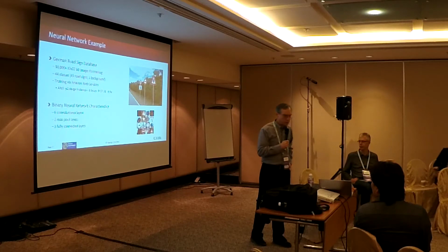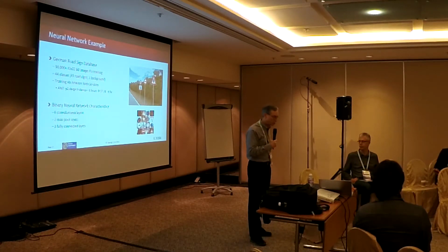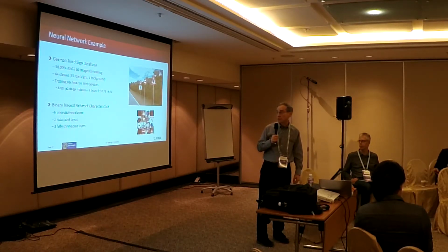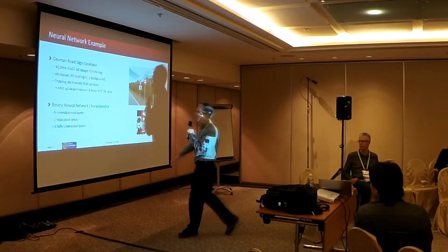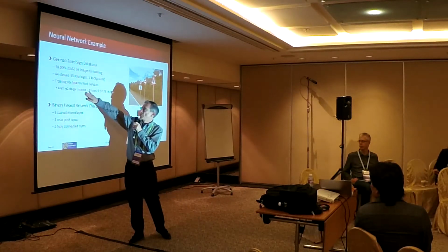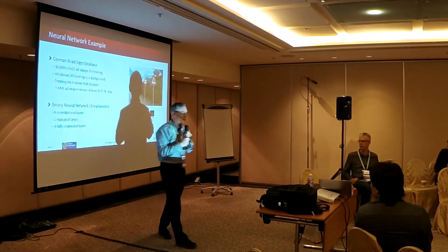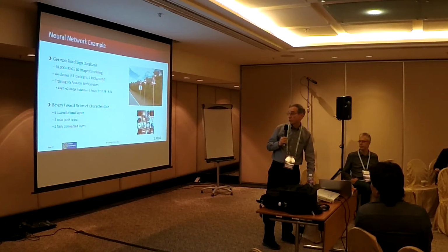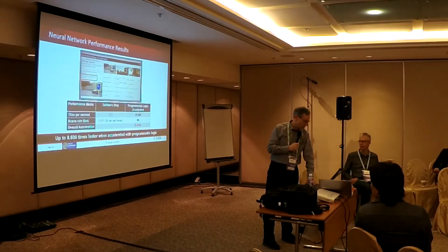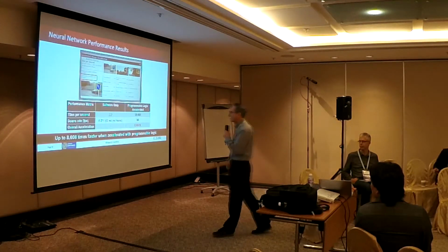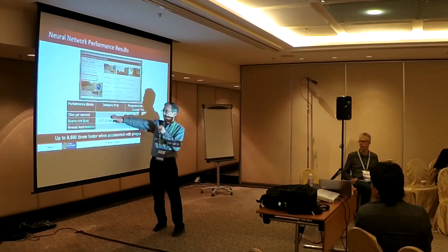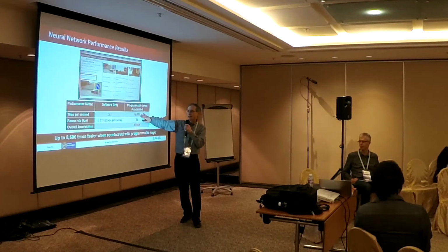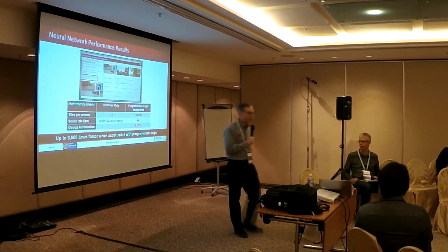The design example, again, I do invite you to come by and see our demo tomorrow, was a German roadside sign database. You can see we did training with 50,000 images, a standard database. People ask, how much does it cost? Amazon Web Services P2 extra-large instance, 8 hours cost about $8. Our network is composed of 6 convolutional layers, 2 max pool layers, 3 fully connected layers. Performance-wise, we ran the application in software. We were able to do 2.2 images per second. Programmable logic, 19,000, an 8,600 times acceleration.